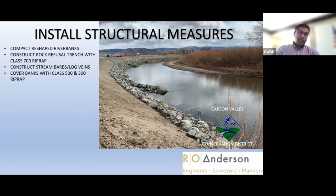the stream. Well, these are actually log vanes. Like I said, those were big logs, about 2 to 3 feet in diameter, and about 40 to 50 feet long. They were installed facing upstream. I think I have another, better, detailed picture of that. So it's about 30 to 45 degrees pointing upstream. Those are very helpful. Sorry, I keep going back.